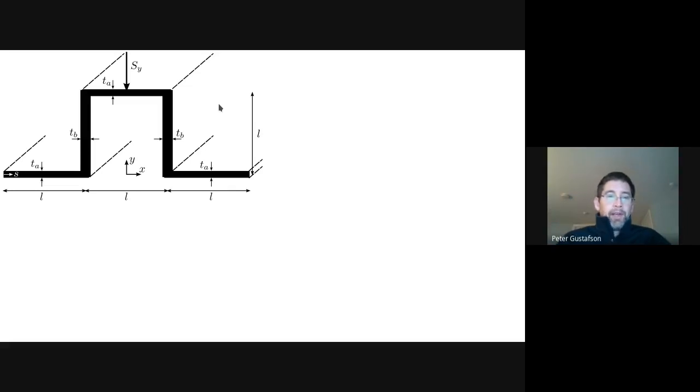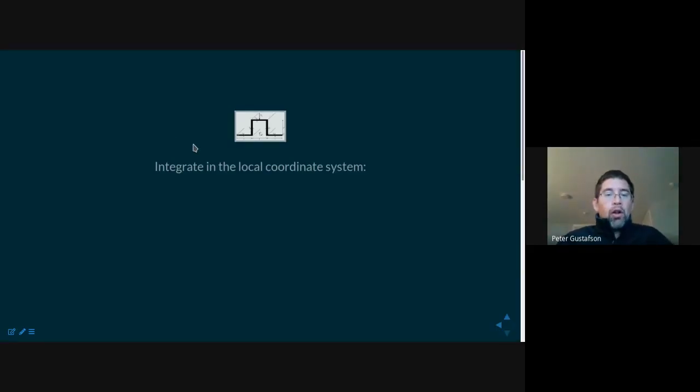It is still a beam. It is still much longer in one direction than it is in any direction within the cross section. But in this case, it has this predominant feature, that is that it has a thin wall. Now, when we have a thin wall, of course, we define that idea of shear flow, which was shear stress times thickness. And then we started to develop equations for how shear flow evolved.